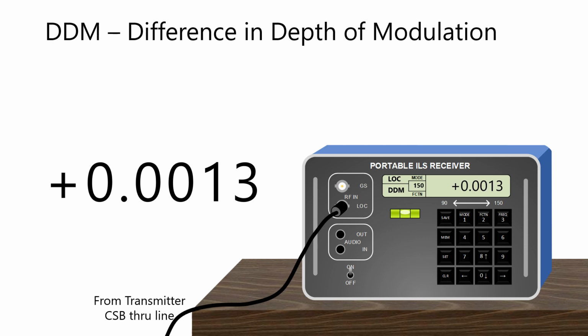On some models of PIRs, the number of averages may be set too high, and a fourth number would appear as the least significant digit, and should be omitted from being recorded or read aloud. Some technicians prefer this setting while others do not. Just keep this in mind as this reading would be read as 1 in the 150, not 13 in the 150.